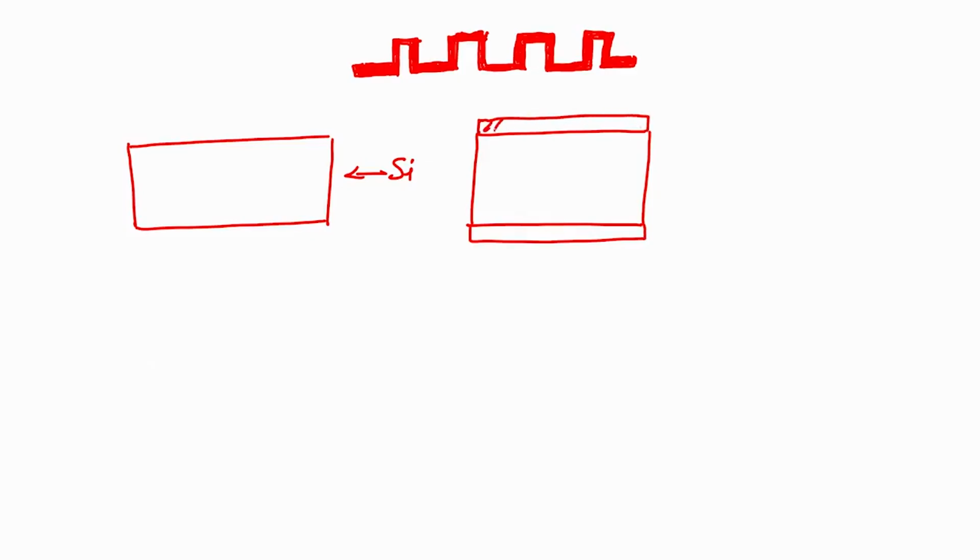All right. So, what will I do? First, you see on the screen, first I will take a silicon wafer. Next I will grow an oxide. Now all of you know how to grow oxide, right? All of you know how to grow oxide using thermal oxidation. So, I am growing SiO2, this is my silicon, this is my SiO2.